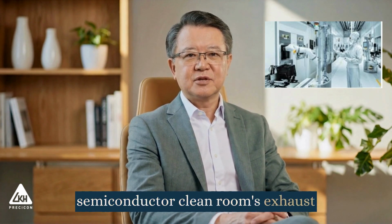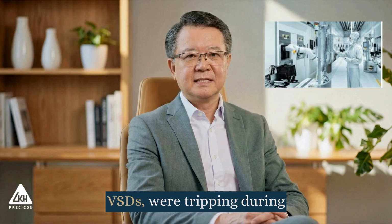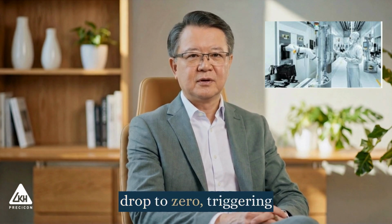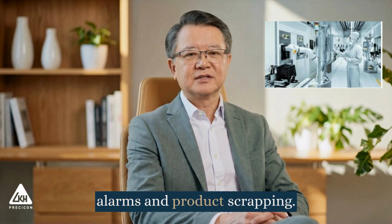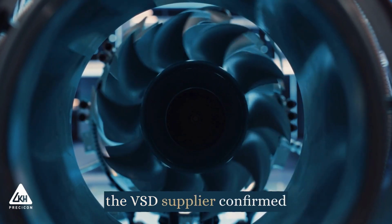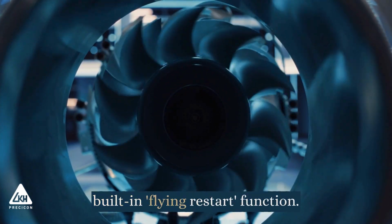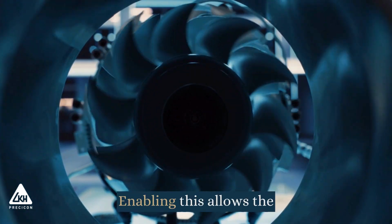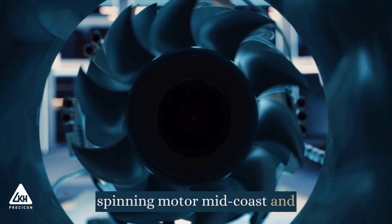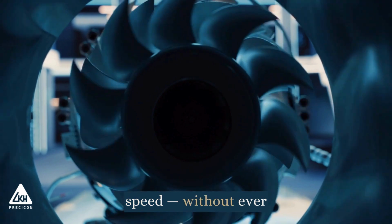Case study 2. A semiconductor cleanroom's exhaust air fans, driven by VSDs, were tripping during voltage dips. Auto restart meant the fans came to a complete stop before restarting, causing air pressure to drop to 0, triggering alarms and product scrapping. The solution cost nothing. The VSD supplier confirmed the drives had a built-in flying restart function. Enabling this allows the VSD to catch the spinning motor mid-coast and accelerate it back to speed without ever reaching 0 pressure.